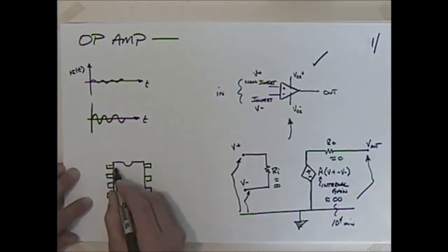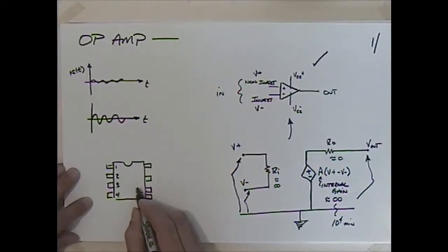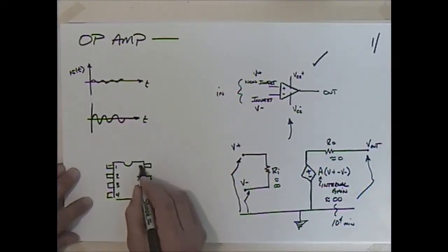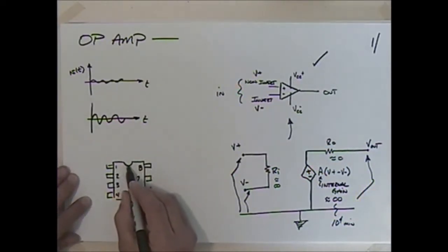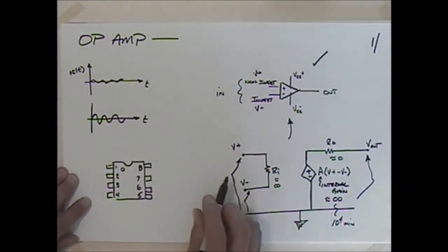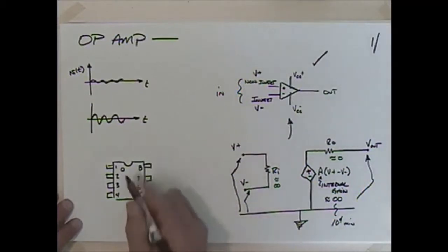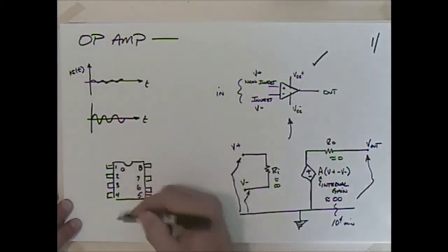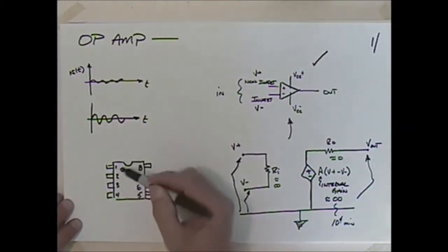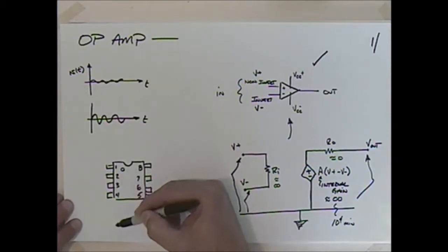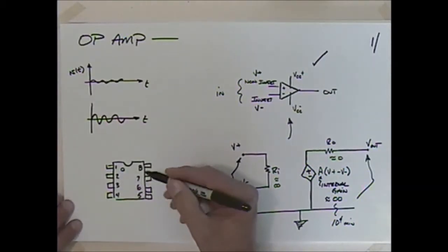So we have pin number 1, 2, 3, 4, and then 5, 6, 7, 8. And you know where 1 is because of this notch. The notch is always there. Sometimes there's a little depressed circle right there, like that. And that, incidentally, in chip numbering is always the same. If they have more pins, the numbers will count larger down here, and you always start back up.